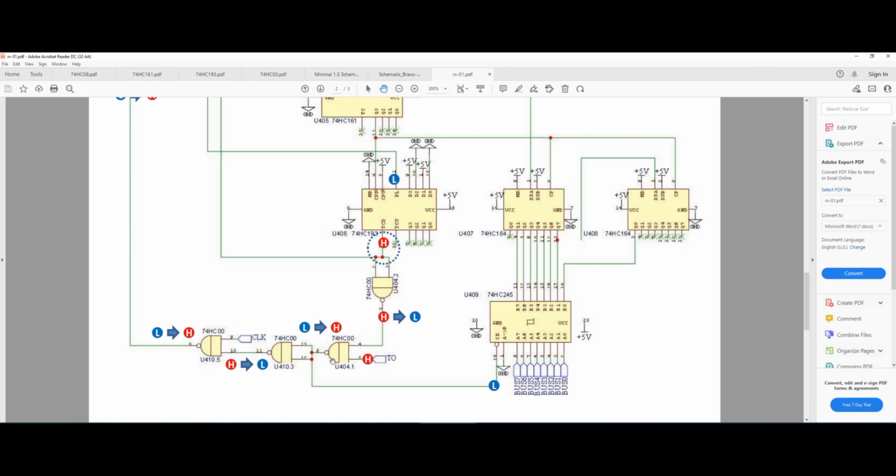So high goes into one NAND gate, and basically that's going to give us a low signal. Remember, for now, just ignore those arrows. The state that we are in is low at this point. I have those arrows for another talk, which we're going to get into in a minute. Basically, those are transitioning in a minute, but for now, the output of this will be low. So what does it mean? That means that we are outputting the content of our transceiver on the bus.